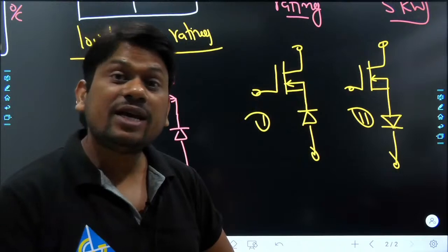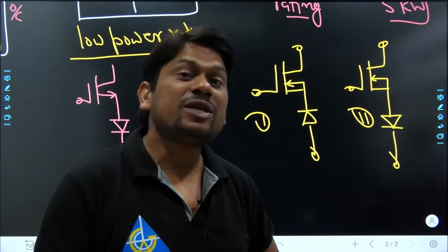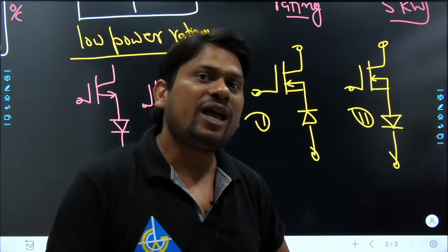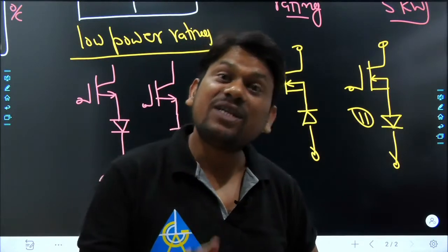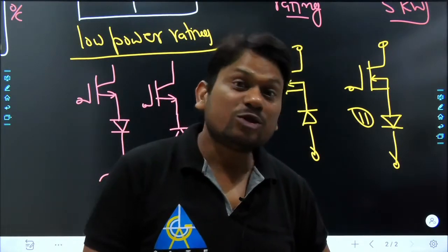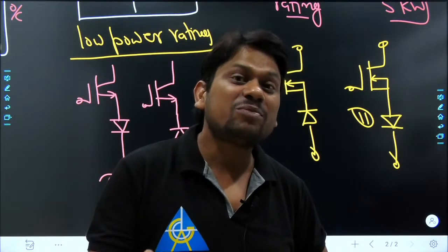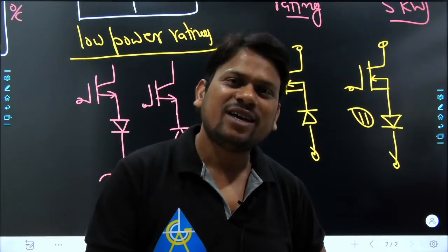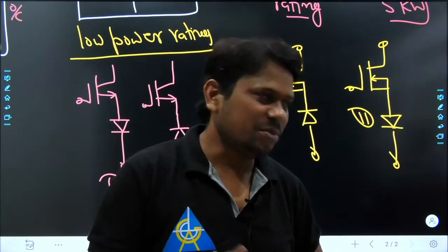How can we achieve that type of job to design an AC to DC converter, especially when we want to control switching losses and conduction losses, as well as control harmonics on the supply side of the AC to DC converter, so that we can easily provide sinusoidal pulse width modulation. This sinusoidal pulse width modulation is really not easy with SCRs, so please keep that in mind.